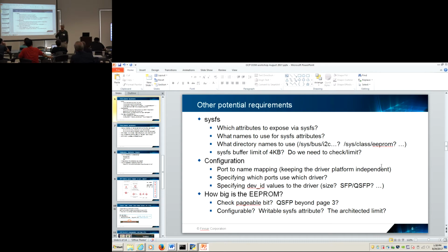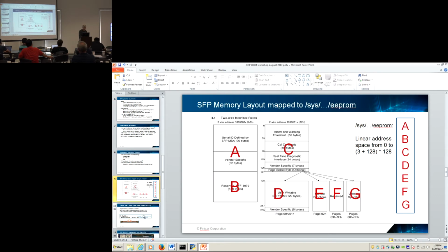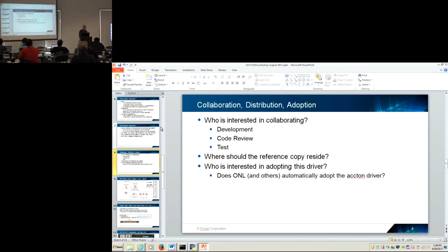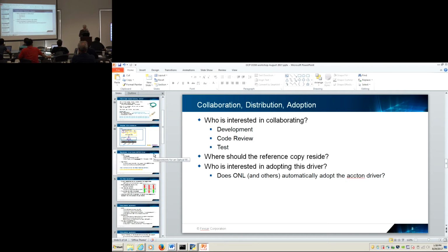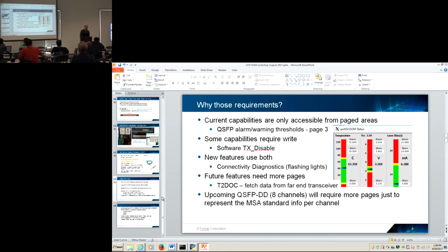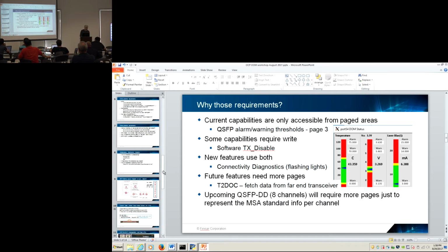You have to decide what that file represents. Does it represent the full address space that's addressable physically for the device? In which case, I think it should be a 64K large file. And it doesn't care about what you're reading and writing, but that's problematic. I don't know of any other arbitrary read and write file in sysfs. The way it's being used, it looks like it's implementing an EEPROM, which is typically a flat memory, so it has a fixed size.